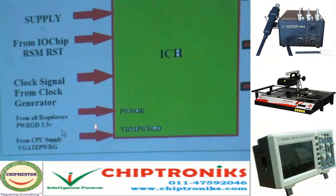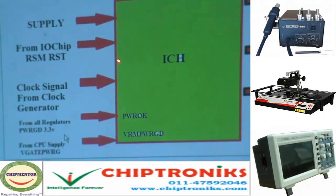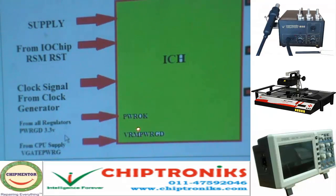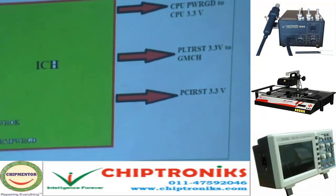So we have checked all the important input signals here: RSM reset 3.3 volt, power OK, V-gate power good, clock signal from clock end and the supply, and the output signals are PLT reset, PCI reset, and CPU power good 3.3 volt.